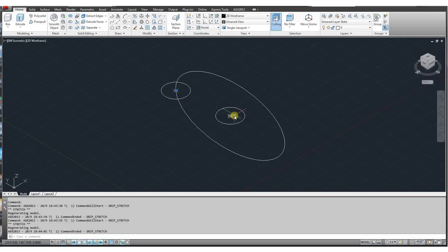So the normal of this center point, which is actually a planar entity, is vertical because it's flat on the xy axis, and the vector between the start point and the radius point creates another line which is, I suppose, one of the u-axis on the plane. So what it does is it uses the cross product between the normal of the start point and the vector between the start and the radius point to create the v-axis of the plane.